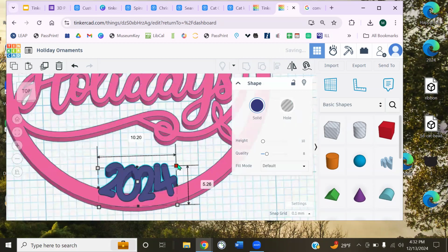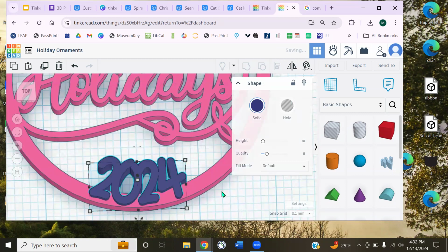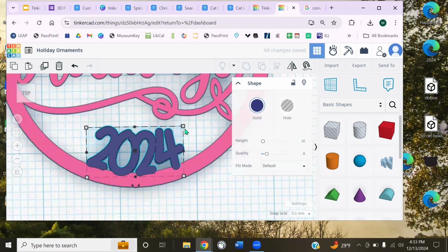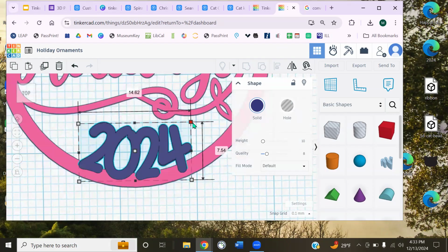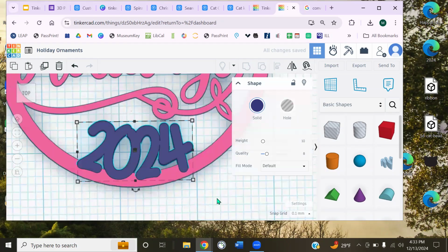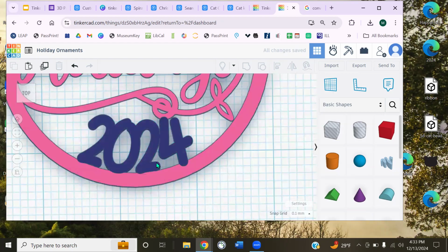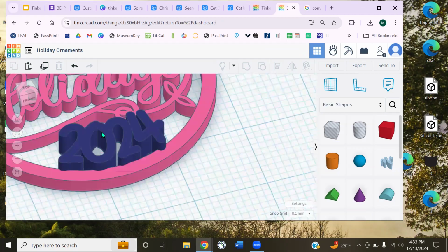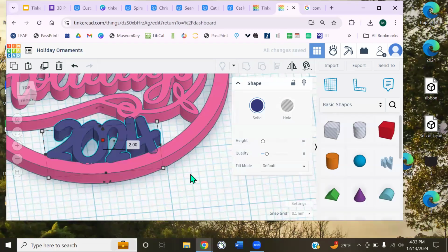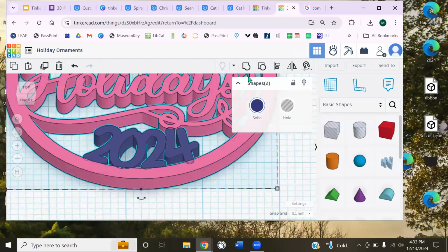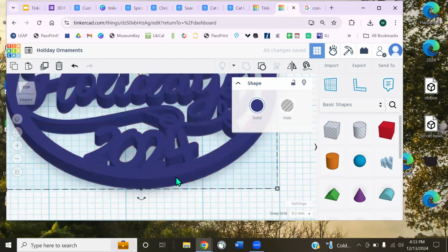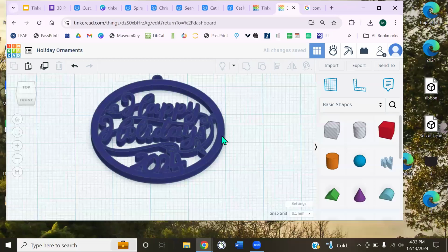I might need to scale it up a little bit. It's a little bit small. Scale it up like that, push it up a little bit. You can see it's pretty well seated. It's going to be stable when we print it out, but we still have a little bit of space that we could go. So maybe I'll boost it up like that. And then that looks pretty good. It's touching on the top too, so it's nice and connected. And then last step, I'm just going to come in, change my Z height down to 2 so everything is flush. And then I can come in and connect everything to do one last object like this. Let that load. And then, yeah, we have a nice little thing. We can print this out now.